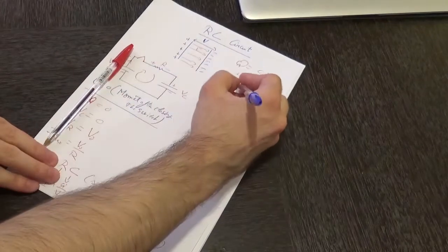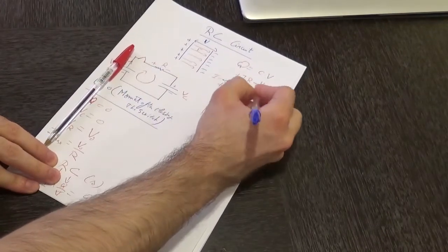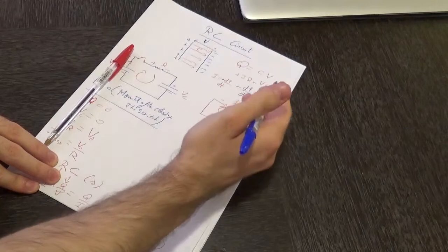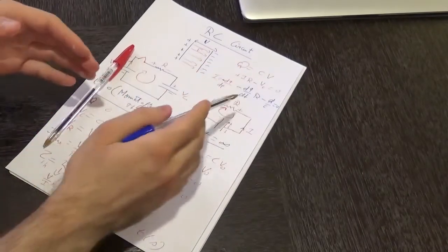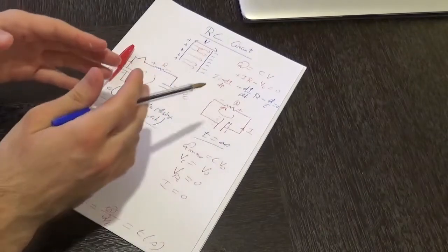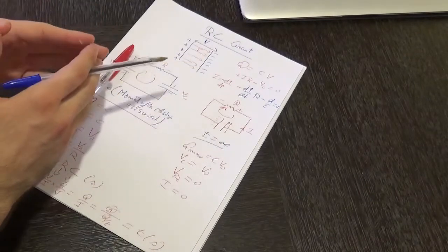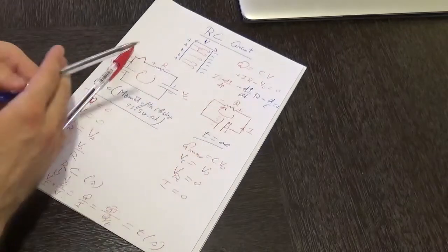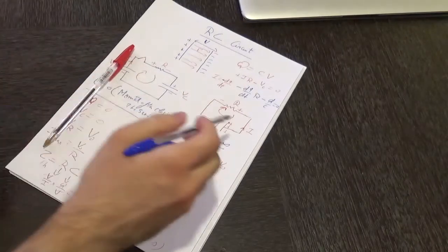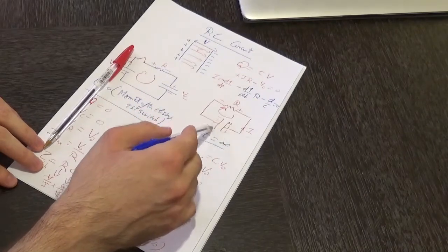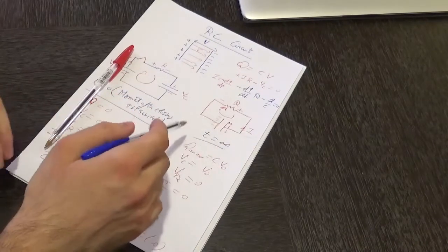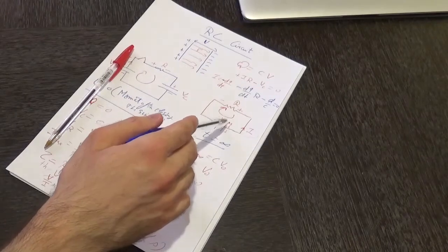Therefore, that equation becomes minus dq over dt times R minus Vc, which is equal to Q over C, equal to 0. And then from that equation you carry on in a similar manner to how we have done before. You are going to do separation of variables in order later on to establish an equation for the electrical current in that circuit, an equation for the amount of charge across that capacitor, and an equation for the voltage across that capacitor.